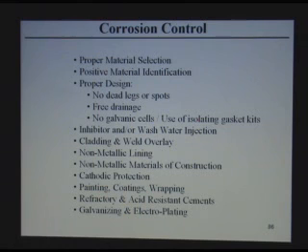And if you use the proper material, actually you're controlling corrosion. We try to avoid corrosion by avoiding dead legs and spots, and by free drainage of equipment. Try to avoid galvanic cells because they generate corrosion. If you have to have a galvanic cell, maybe you have to put isolating gaskets, electrical isolation between the noble material and the less noble material. And these kits are available in the market.